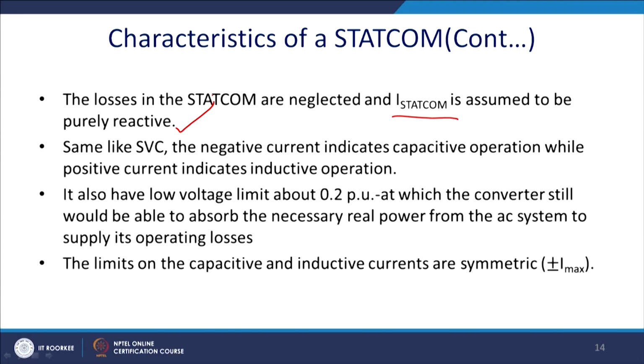So, what can we conclude about the characteristics of the system? Losses in the Statcom are neglected, and the Statcom is assumed to be purely reactive. Same as the SVC, negative current indicates capacitive operation while positive current indicates inductive operation. This is the same convention we will follow.